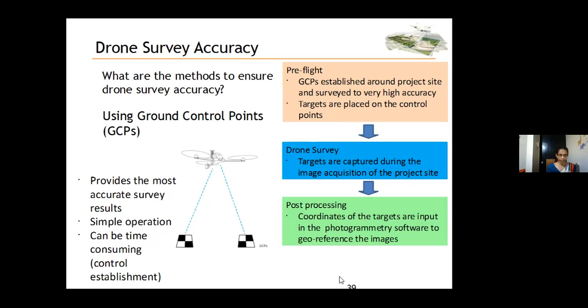But if we want repeatability for change detection, or to compare your result to those collected from another survey via drone or other methods, we want to georeference your imagery and surface model to real world coordinates with high confidence.